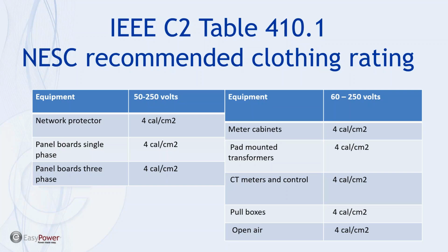So the possible option in this case would be to label anything. I guess the first place to start is if my qualified workers are going to be having their daily wear rated at a minimum of 4 calories, then I could safely label these elements in my system without necessarily going into an extensive analysis of all the different loads in these cases.